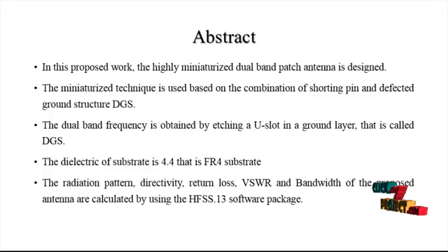In this proposed work, the highly miniaturized dual patch antenna was designed using the HFSS software. The miniaturization technique is based on the combination of a shorting pin and a defected ground structure, that is called a DGS. The shorting pin connects the ground plane and the patch antenna.